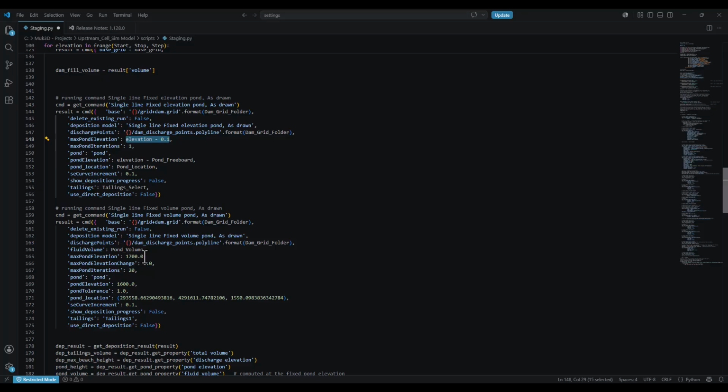This is because when the grid resamples your dam structure, where the actual structure is built on the grid, if your grid spacing is half of the crest width or less, you're definitely going to get 2 data points on top of that crest, and therefore you're going to have enough detail in the grid to have containment up to that elevation. Otherwise, your containment is going to be likely slightly below your crest elevation.